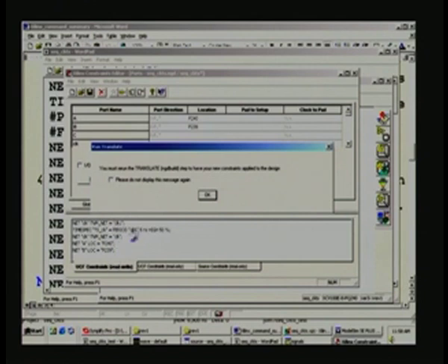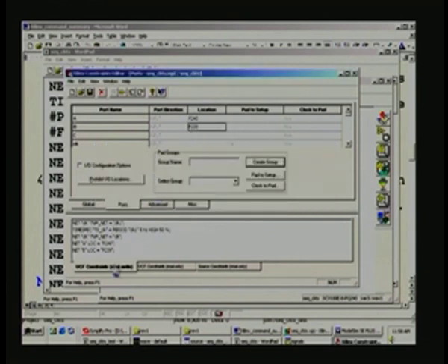So, in order to do this, you have to go back, prior to back annotation, straight away to the implementation, the Xilinx place and route implementation. Start from the implementation, then do the back annotation once again, and then make sure the functionality is okay with the pins, and that is how you have to go. That is a time consuming thing, and it is precisely the same that we have already followed. Therefore, that particular aspect will not be shown, and it is enough if you just see a UCF file. With that, I think you will be in a position to remap your IOs as well as the clock.